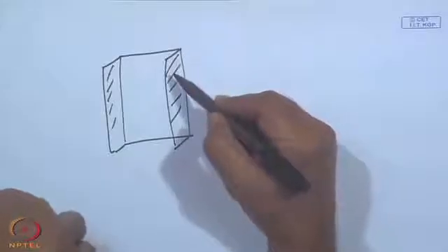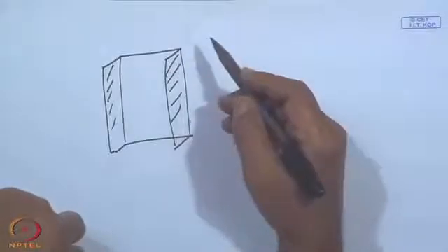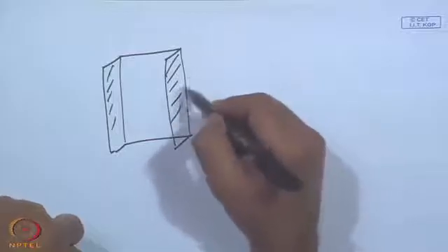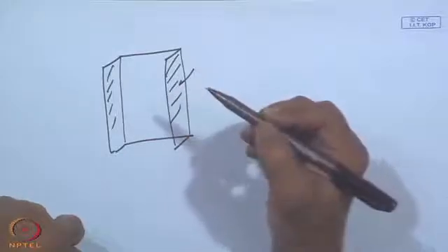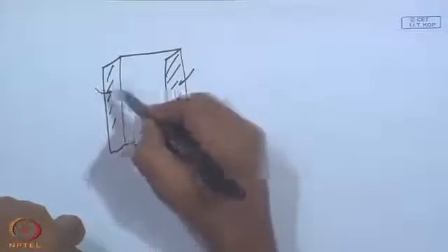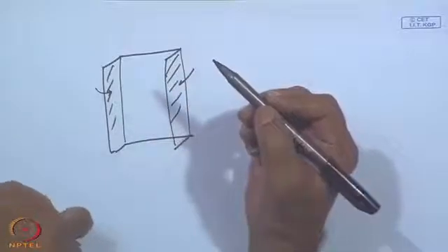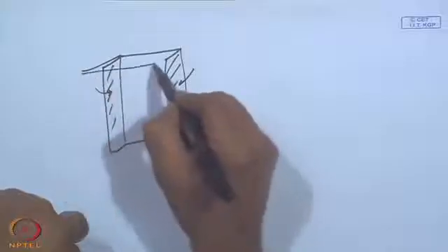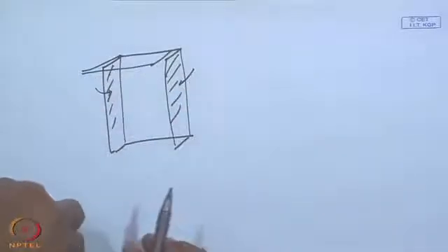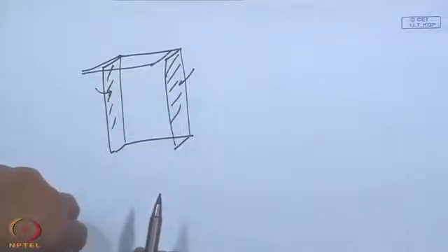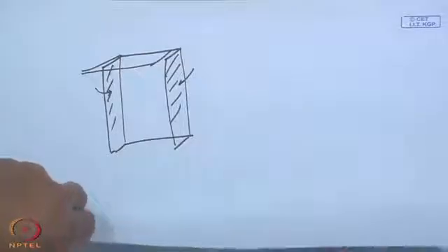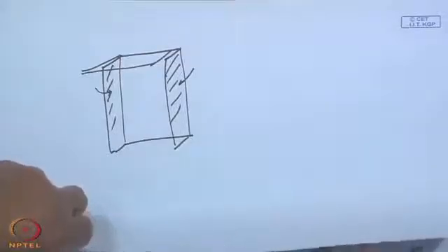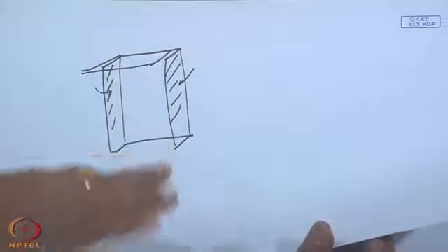But then these wing walls will prevent a lot of radiation entering in the morning if it is in the east, and in the afternoon if this is in the west. So, in conjunction with an overhang, effectively it looks like a box type of window which will be completely shaded. Whether you desire it or not depends upon the season, climate and your objective.